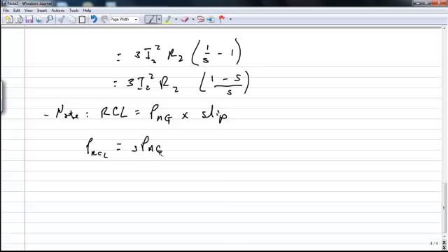Therefore, the lower the slip, the lower the rotor loss in the machine. Also, if the machine is not turning, then the slip equals 1, and all the power is completely consumed in the rotor because there would be no converted power.